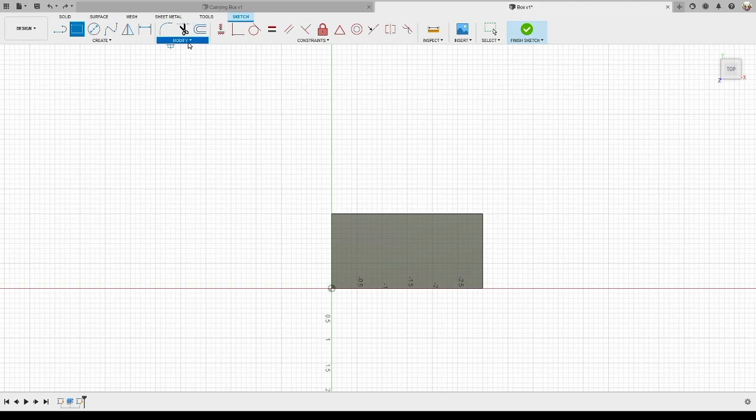I was talking about the offset tool earlier. This one right here. If you select the edge that you want to offset, you can make it go in or out. Say you want it to be a frame, outwards. But I want to make it go in negative 0.05. If you put the negative, that says that I want it to be within this box. If you were to go out, it would be a positive number. So I want it to be negative 0.05. That's what my thickness is going to be.